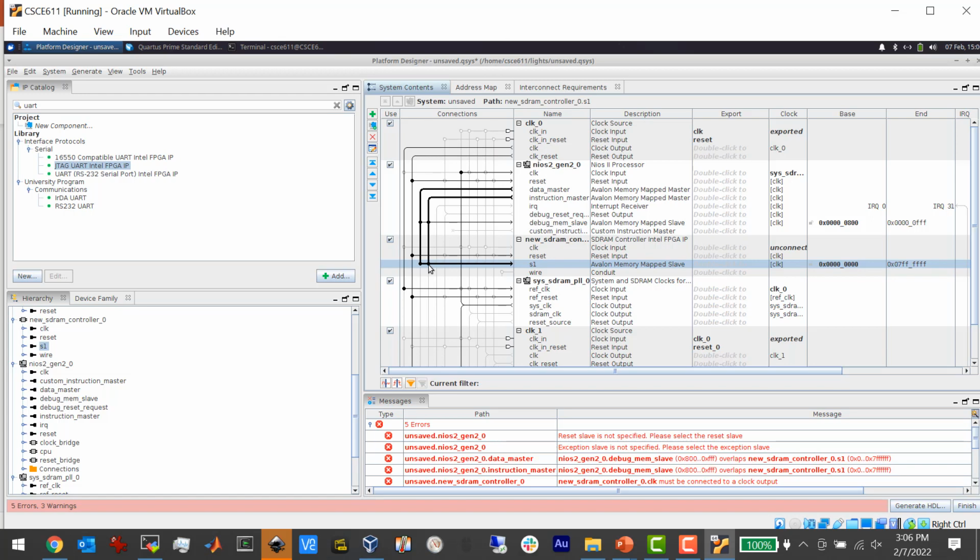You know, what's funny is that the older versions of the software didn't require this, and there may be a way to work around this actually that I haven't found yet. But right now, this is the only way to do it, because if you don't add this, you get all those DRAM errors. Let me show you. Wait, actually, let's go back to Quartus, and I'll show you exactly what I'm talking about.